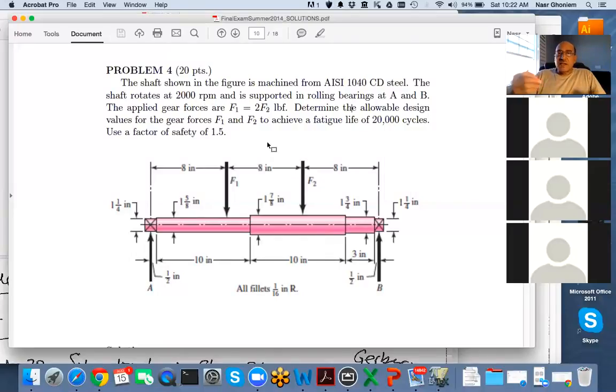As we've seen in the summary, in the intermediate range, which is high cycle fatigue, S is equal to A times N to the power B. So I need to figure out what A is and what B is. Now in the design world, there might be more complications. Complications would be the fatigue factors. What are the fatigue factors for this shaft? We know the endurance limit or the fatigue strength is reduced as a result of machining the surface, temperature, and size. So there are 5 or 6 factors in the book that might need to be determined.